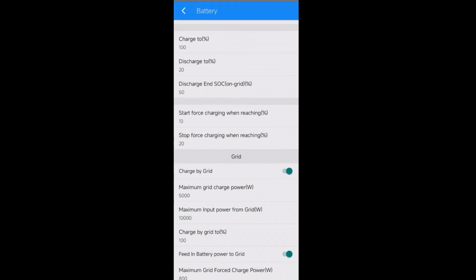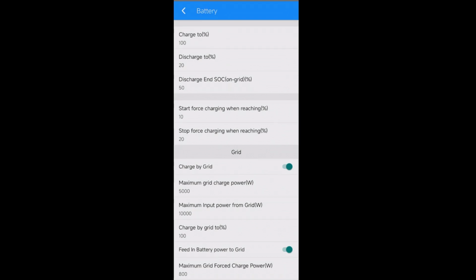This function is to protect a battery, not used for other purposes. On our app, there is a fast charge setting available, and on the BMS side, I think a good BMS also has its own logic of fast charging. For example, when the cell voltage is very low, the BMS will check and report to the inverter.